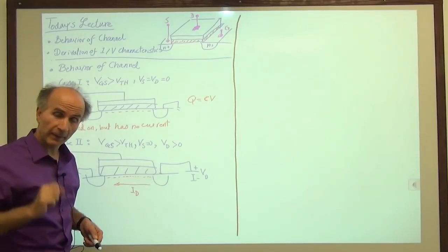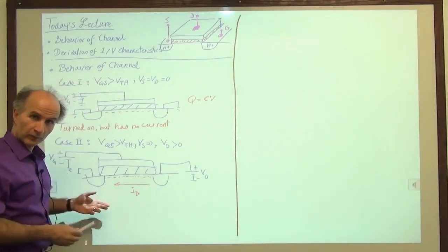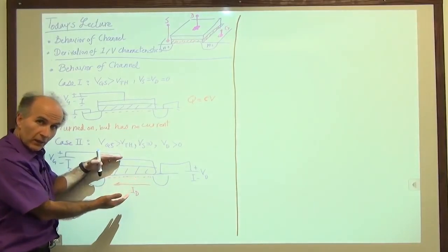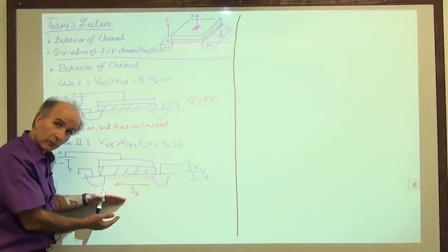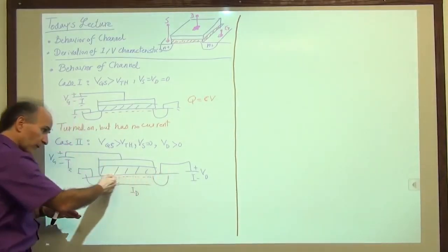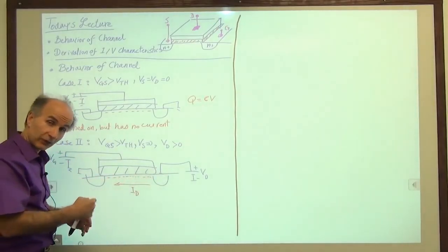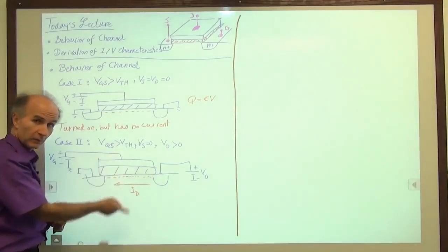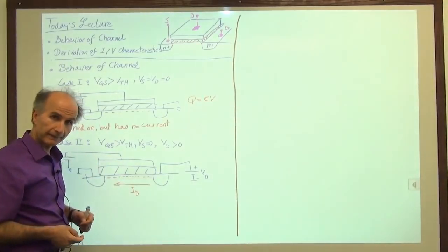So that's a weird capacitor. Ordinary capacitors wouldn't be like this. You had one plate here, that's it. But now, we have a plate here, but in this plate, what have we done? We are allowing a current to flow through a resistive path. And that creates a voltage drop this way, in addition to whatever we applied between the two plates.